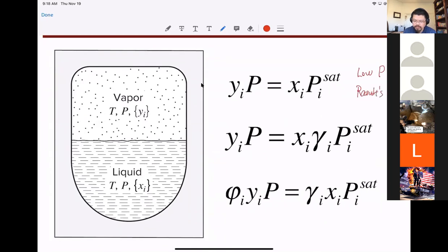And then for the liquid phase, we are going to use the ideal solution assumption. And moving to the next step, we cannot assume the ideal solution for the liquid, then we need to look for the activity coefficient. Then for the most general case, we have to treat both liquid and the vapor as real and complicated phases, and we need to calculate the activity coefficient as well as the fugacity coefficient.